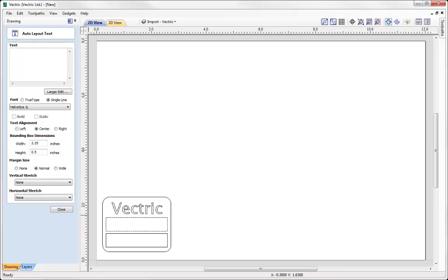So all we need to do then is simply enter in variables. That will be picked up by the plate production tool for the text that needs to change within the badge. So to do this, we just simply start by entering some text. Now when we are creating variables, you need to start the text off with a double exclamation mark, and then enter the text that you wish to put in, followed by another double exclamation mark. And that's the only way that the plate production will be able to pick these variables up.